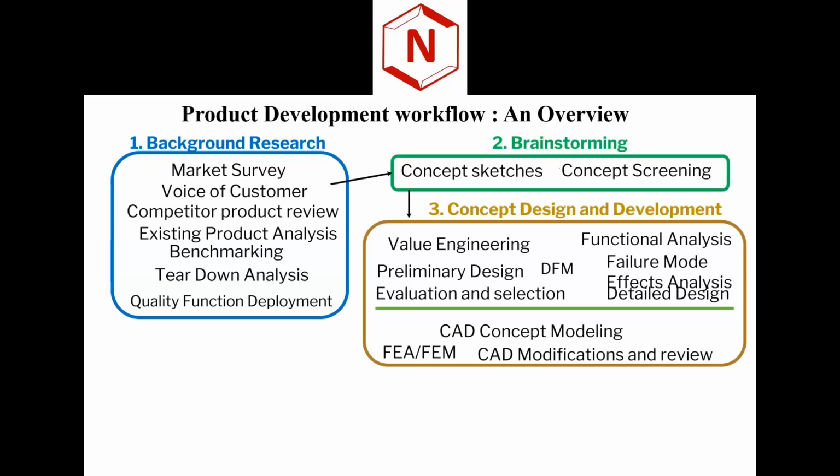Once the concept is developed, we further develop it in more detail using CAD modeling and finite element analysis, modifying the design based on the stress analysis. We will also do the value engineering of the existing product. Value engineering is nothing but we try to maximize the value provided by the product and minimize the cost. We will also do design for manufacturing considerations. Ultimately we need to manufacture the product and release it into the market, so the manufacturing constraints also we will bring in,